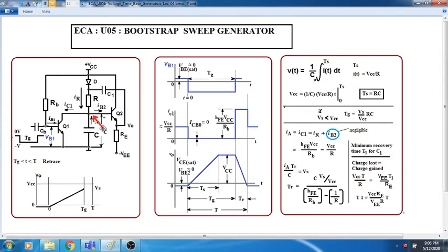Okay. Now the capacitor started charging towards Vcc. As soon as the capacitor voltage increases, remember Q1 is cut off, because as soon as the gate pulse is given, Q1 is cut off. When the capacitor voltage rises slightly, then please observe that the voltage here increases, it becomes slightly positive. The voltage at the output also becomes positive. Obviously this is the voltage available at the output.